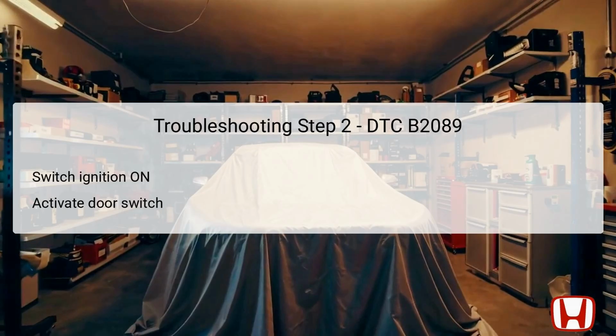Specifically, you will need to operate the open side of the right power sliding door switch for at least 3 continuous seconds. This action helps the control modules assess the switch's functionality and note any discrepancies in performance or signal transmission. Observing the response during this activation phase is critical for troubleshooting.